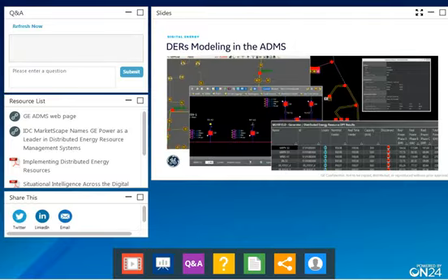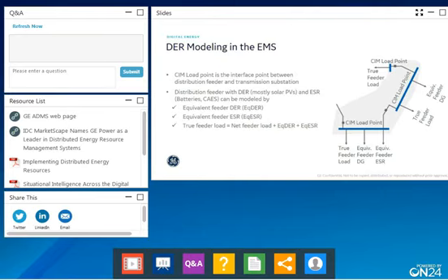Then through the EMS, obviously, the DERs need to be modeled too, right? So at the transmission level, a big PV or a big wind farm or a big storage unit is modeled. But also you want at the boundary to be able to model within your EMS at transmission level what's happening downstairs, what's happening in terms of the feeder, not just feeder load, but feeder equivalent generation and feeder equivalent storage. And this takes some modeling into the systems, but also some tight discussions between the TSOs and the DSOs. And that's, I guess, a good segue to the next part. Back to you, Dave.